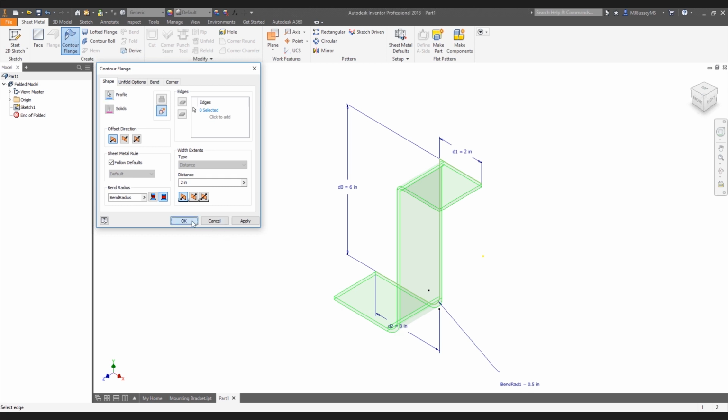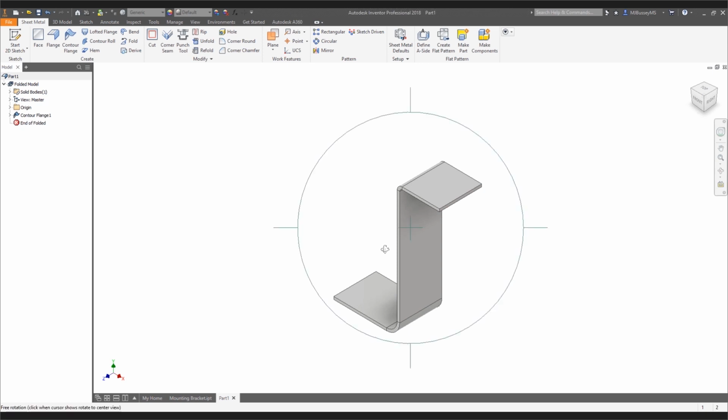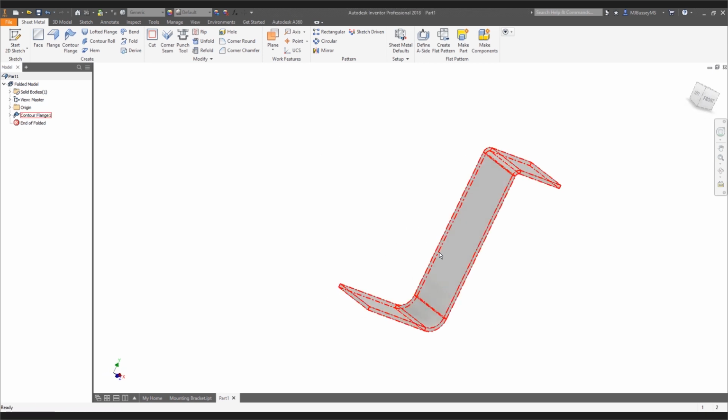Okay. And one of the little inside things about Inventor: when Inventor creates a flat pattern, it's actually using a feature recognition engine under the hood. Now, when we create our own bends with Inventor, we put a hidden annotation on there, or attribute, if you know the Inventor API, that says this is a bend, treat it like a bend.